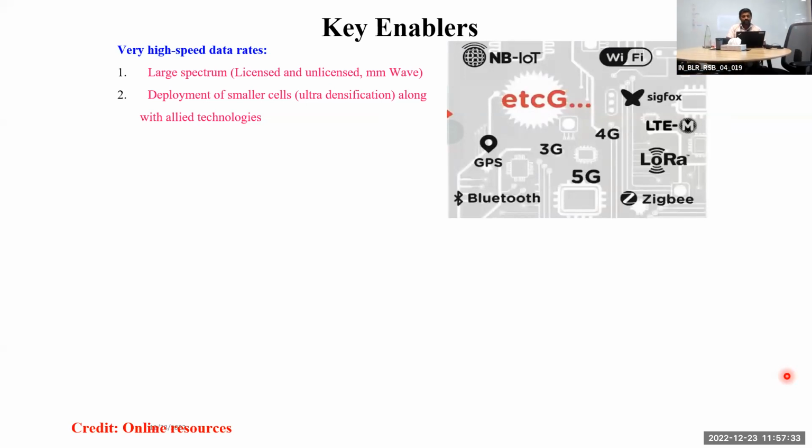But in 5G you cannot do that, because 3.5 gigahertz is almost 3 to 4 times that of 900 megahertz, right? So the wavelength reduces and path loss increases. I will shortly touch upon why frequency is important. So you need to have multiple sites, say within 20 kilometers you need at least 5 or 6 sites, even for the highways. So that's the scenario now.